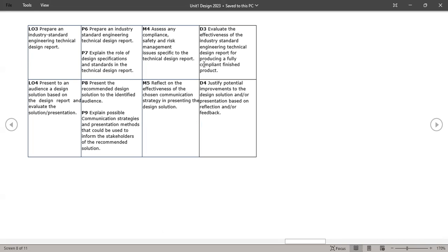So again, we're really taking our original design spec and what would be required to have a fully compliant product spec in terms of all the testing that's required in terms of building a fully compliant product that can be sold on the open market, so that you've identified the voltages, the currents, the temperature rating, all the safety requirements.